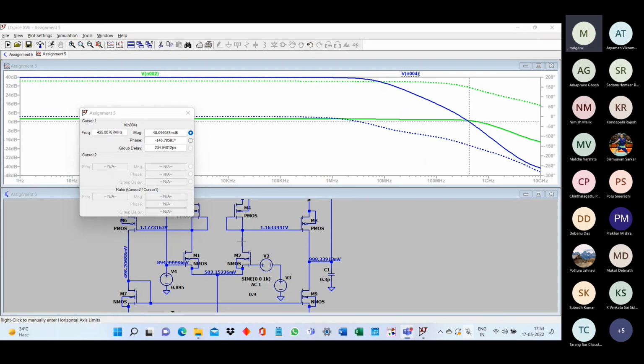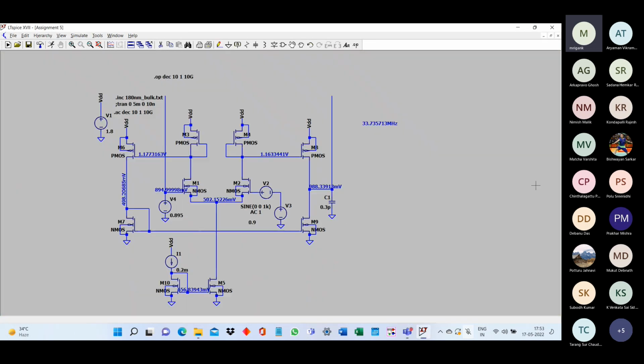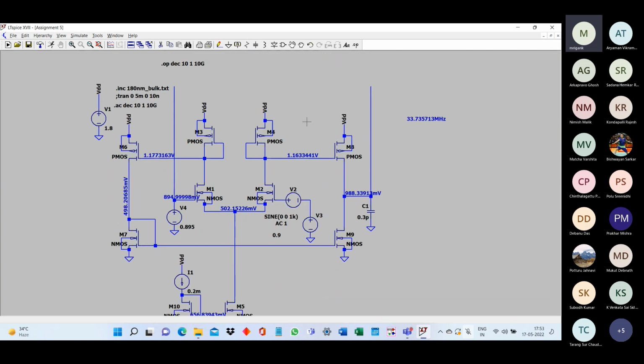And once again, you understand the reason why we keep a good phase margin: because there are variation effects, whatever phase margin you are setting in the actual design, after fabrication you may get a different phase margin. It may, in fact, end up violating your phase margin. Therefore, considering the variation effects of the actual circuits, we should also keep a good margin. So the earlier value was safe because, although the bandwidth was lower, the phase margin was good. So we can keep that value also.